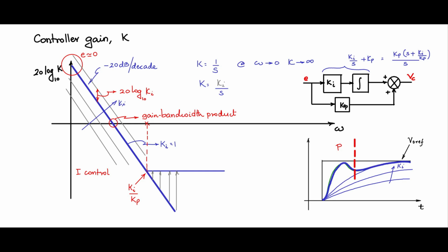And then Kp is only going to improve the dynamics. Steady state, Kp is not going to touch, because Kp comes only in the higher frequency zone. As the low frequency comes into the picture, it is only I control. So you have taken care of I control. First you have to take care of the I control and fix your steady state response. So once the steady state response is fixed, then you try to pull up the dynamics by introducing Kp.